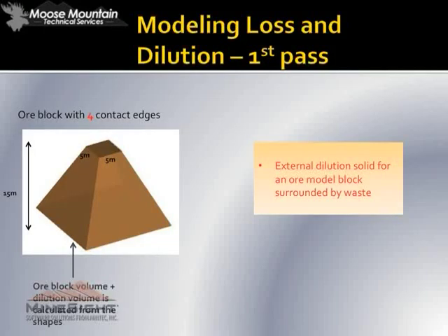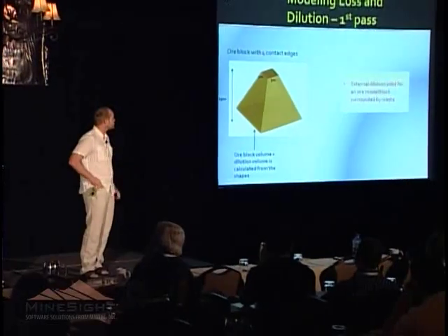So I'm just going to focus on this case study. What are some of the tools that we used? Even some of the basics. I'm a visual person, so assume you're going to dig up to an ore block with a large shovel on a 15-meter bench and stop at the ore contact. So you have a little 5 by 5 meter block, which is our block size in the model, and it's 15 meters high. That was the first pass that we got.